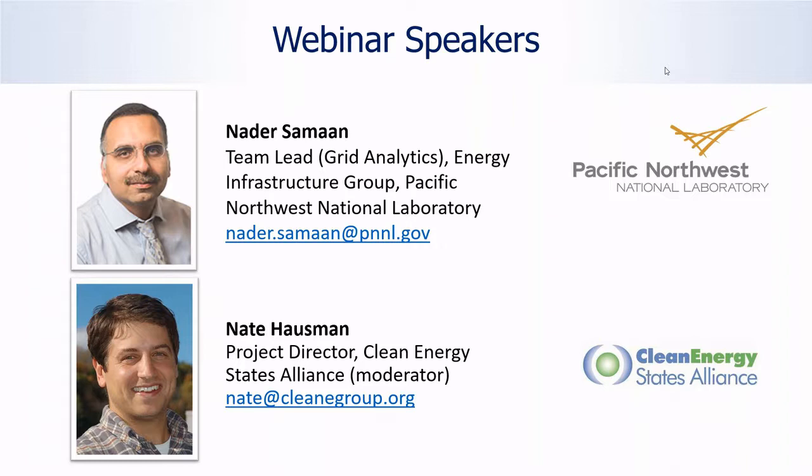We are simply honoring any decision. So it's kind of real power and reactive power decoupled from each other. But I agree that having storage as part of that would be more like an ancillary service that storage is providing in addition to real power, which may have more value for storage, and could be part of this optimization. So reactive support could be coming not only from smart inverters from PV, but also from smart inverters that connect storage with the grid.